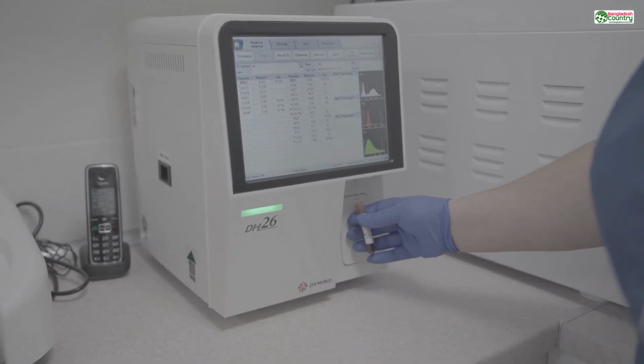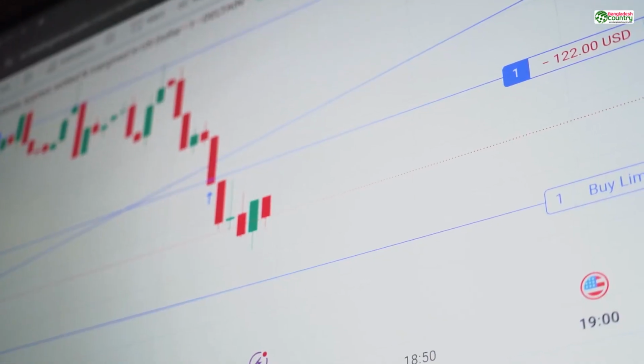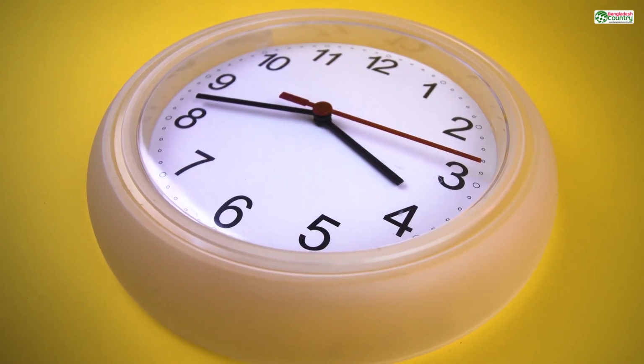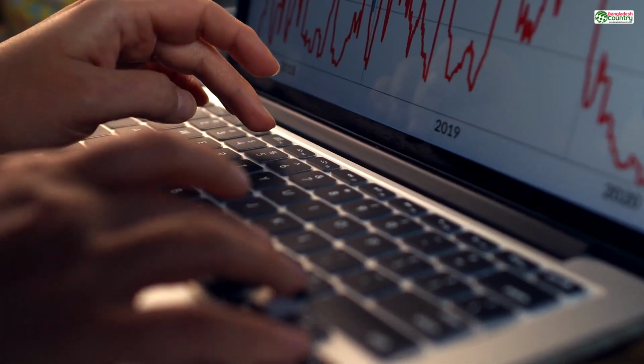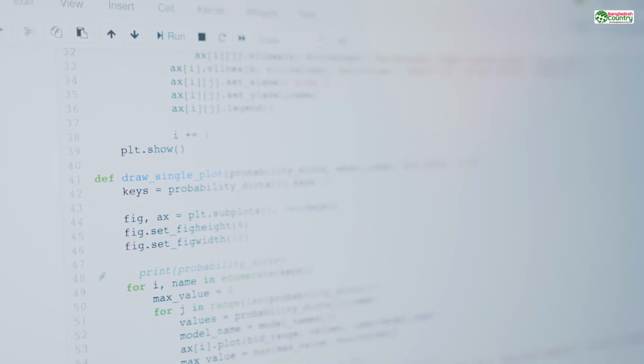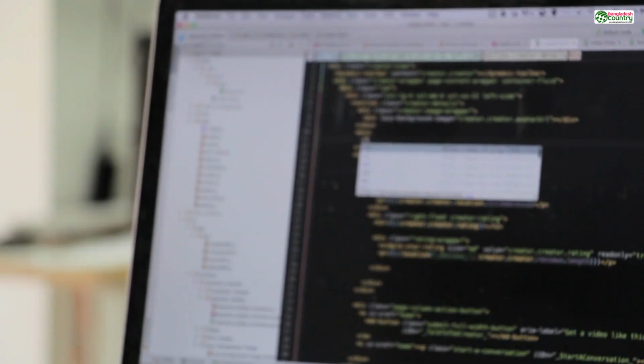So, you've run the analysis and you've found the problems. Now it's time to get out the digital scalpel. Let's say the analysis tool has highlighted the edges of a simple circular hole. In most programs, you can simply select that entire loop of edges and hit a Fill or Make Face command. The software will stretch a new piece of digital skin over the opening, healing it instantly.